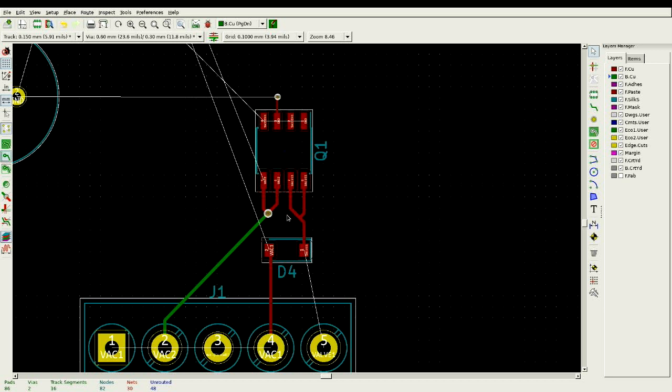You need to finish all the underside traces before you do the ground plane? No. If you do traces afterwards, then the ground plane will magically get out of the way. You tell it to re-pour itself. You just hit the B button, it re-pours itself and fixes itself.